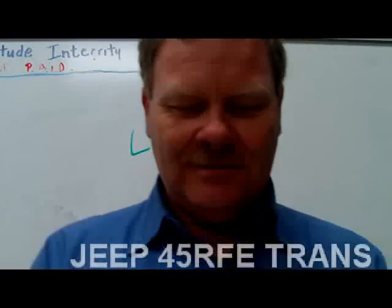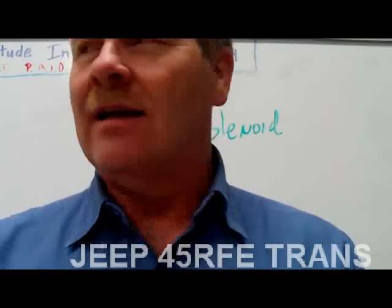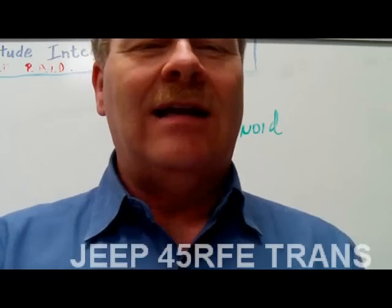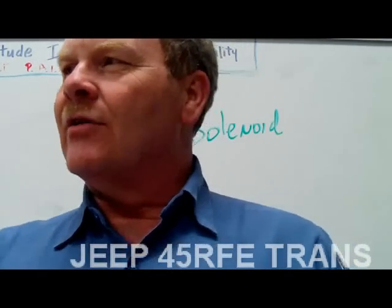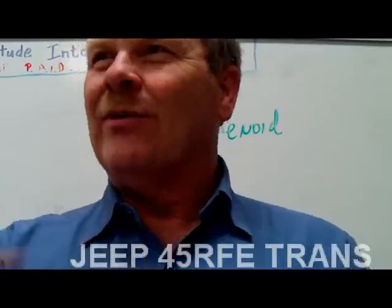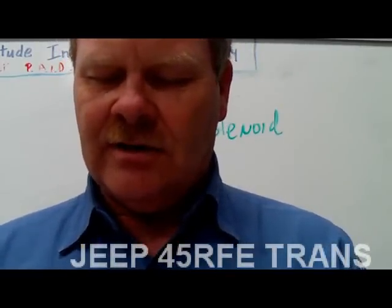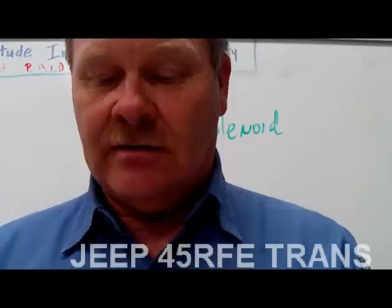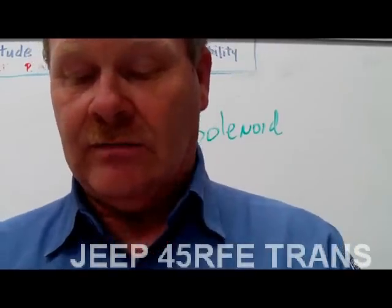Well, if they had one that said RF, then I'd think right front. Yeah, exactly. But they didn't. When I looked, it said left rear solenoid. I said, wait a minute, there's no left rear solenoid, so low reverse. The transmission controller keeps the LRCC solenoid at full on, which is low reverse and converter clutch, I guess.